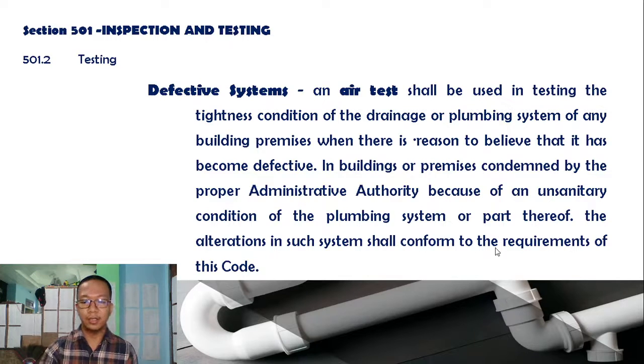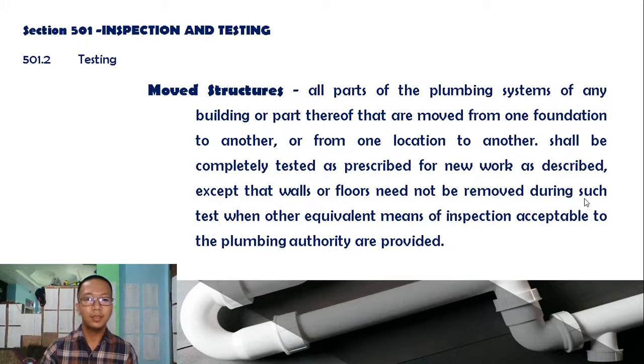Next, moved structures. All parts of the plumbing systems of any building or part thereof that are moved from one foundation to another or from one location to another shall be completely tested as prescribed for new work, except that walls or floors need not be removed during such test when other equivalent means of inspection accepted to the plumbing authority are provided.